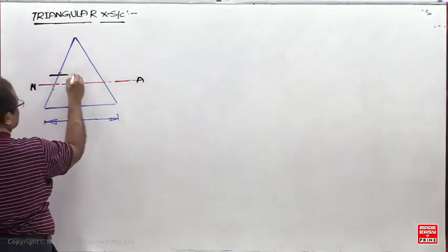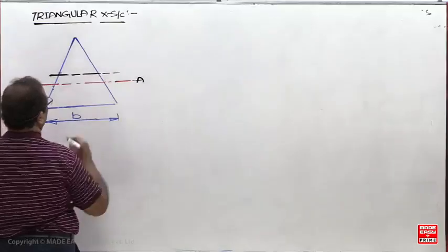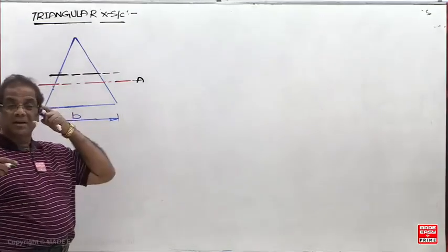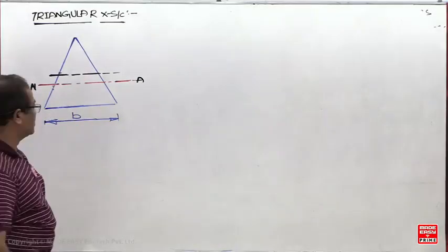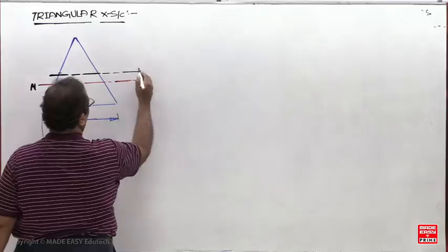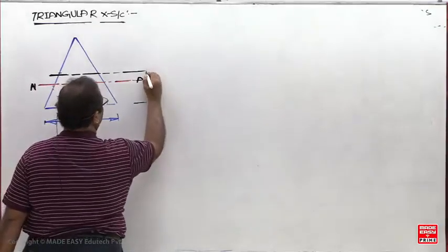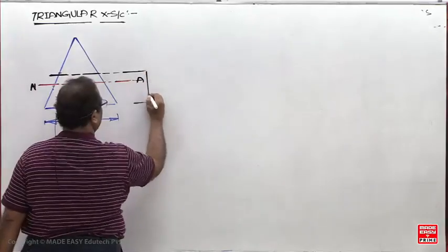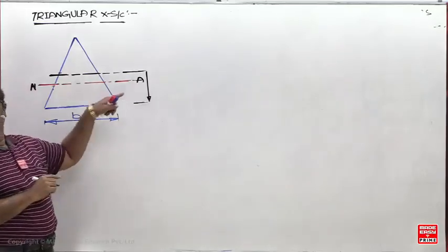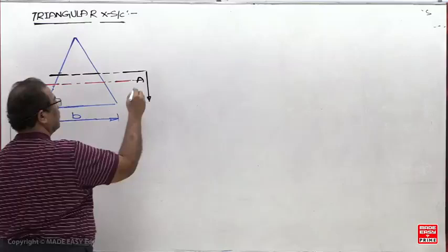Now I am drawing the shear stress variation for triangular. Remaining all have the maximum at the neutral axis, but in triangular and SD it is not maximum at the neutral axis. If anybody wants to derive it, the same thing you have to do. But here the width is varying, whereas in the rectangular case, the width was constant.